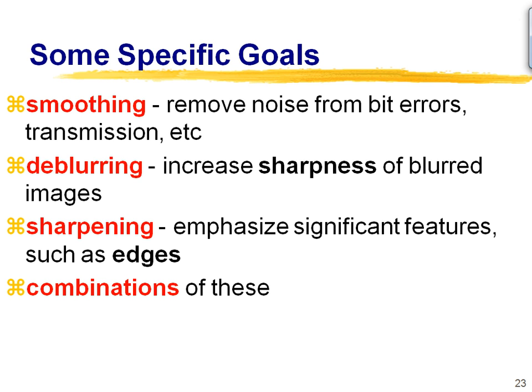So obviously I don't have a nice gradual change anymore. Now in this case, this is an extreme situation, right? If I think of my noise model as this additive zero mean ergodic noise that we have thought about before, then of course I should see simply some spikes come up every once in a while. Right? Now if I want to get rid of noise, well, I would expect that somehow I should be able to get rid of all these spikes and come back to this original line that I have, right? And I can do that by essentially a smoothing operation.